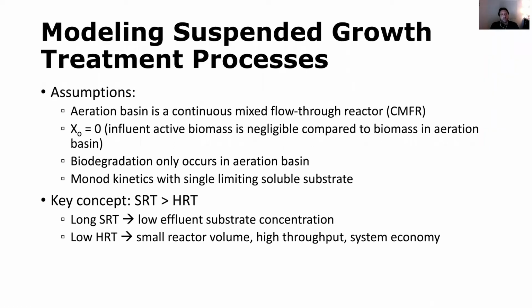So to model suspended growth treatment processes, we can use a few basic assumptions with a mass balance approach. The first assumption is that we'll treat the aeration basin as if it were a continuously mixed flow-through reactor. We'll also assume that the influent has a very low concentration of active biomass relative to the aeration basin.